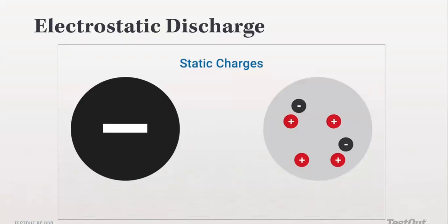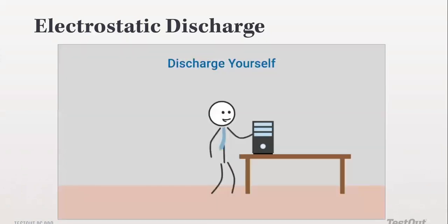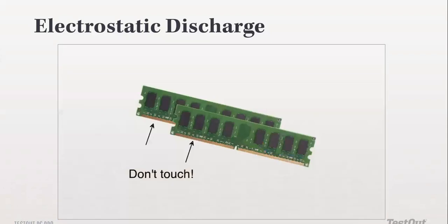So you need to know that the amount of electricity that is required to damage an electrical component is not even one that you as a human can feel. So don't think that because you cannot feel that current, it is not enough to damage a component. This is why we always advise that you should not touch devices at the level of the pins. If you look right here, you see these pins here. We always advise that you should not touch them with your hands, because you might have electricity built up in you that is just enough to damage these components without you even knowing.